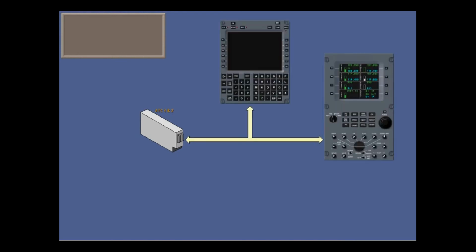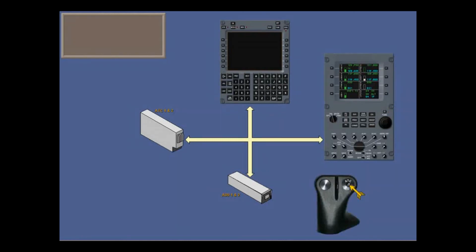The operating modes of the transponders are controlled by the ARC2s and the FMS. The air data units also supply altitude data. Squawking ident back to ATC can be done from the ID button on the ARC2, although it's usually done from the ATC ident remote buttons on the control wheels. When ident is activated, the transponder will squawk ident for about 17 seconds.